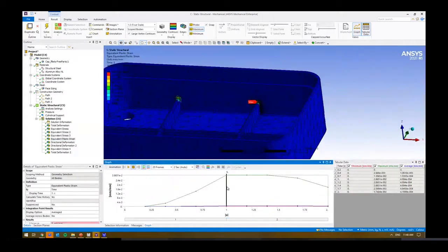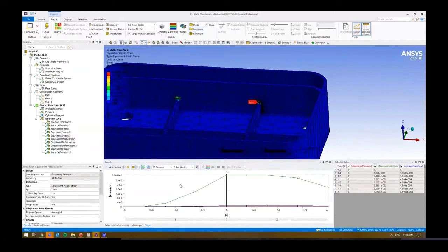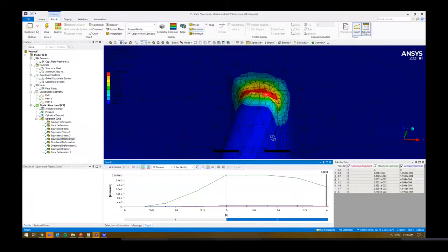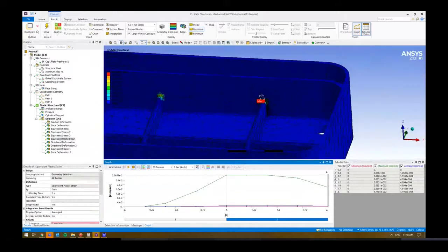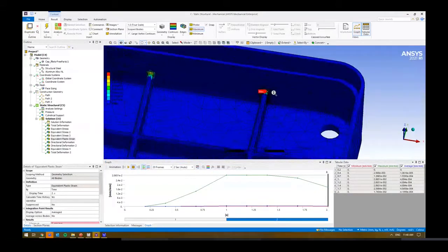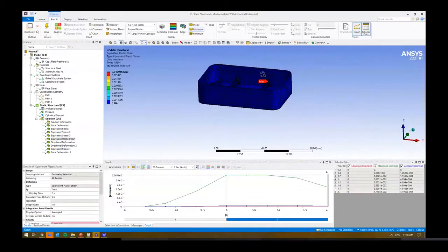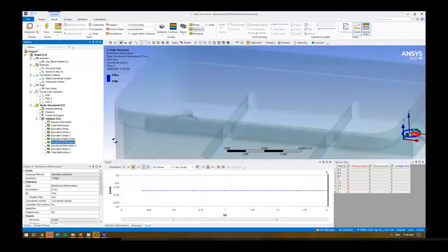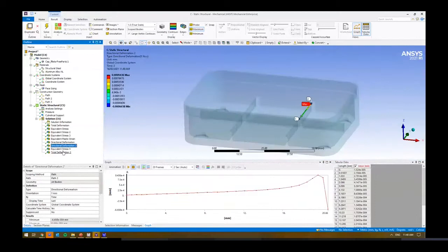If we have a look at our actual plastic strain, by the end of the first step we've got plastic strain around this region, and when we unload our object, we've still got some local strain around there, right? Everything else is okay, but locally around this region, we definitely want to go back and make some changes, right? So good.